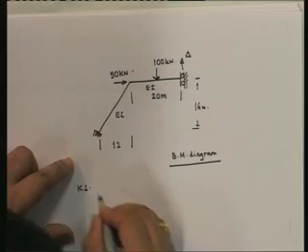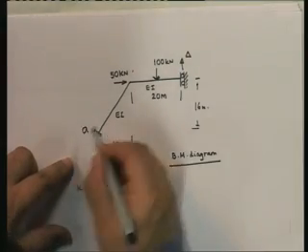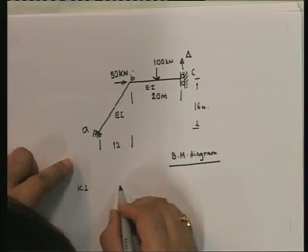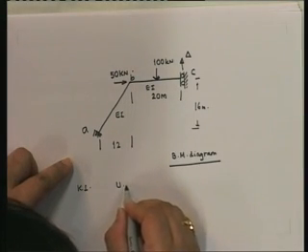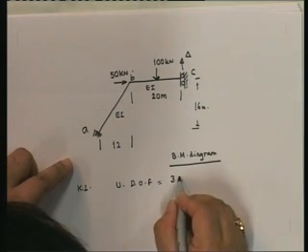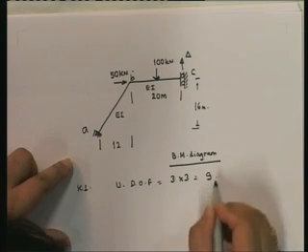Okay. So once you have this displacement method, let us go through some of the steps for this particular problem that we have identified. Okay. First, degrees of freedom. Determine the kinematic indeterminacy. How do we go about it? 1, 2, 3. How many degrees? Joints are 3, so unrestrained degrees of freedom are equal to 3 into 3, 9.